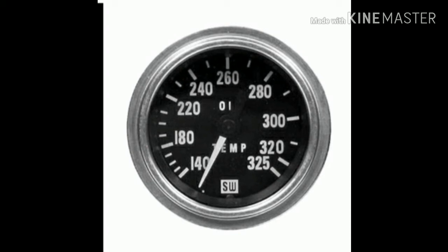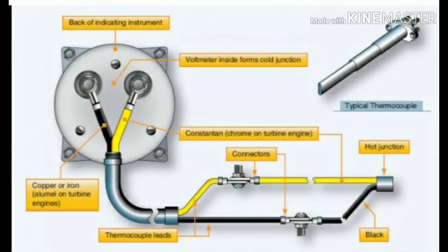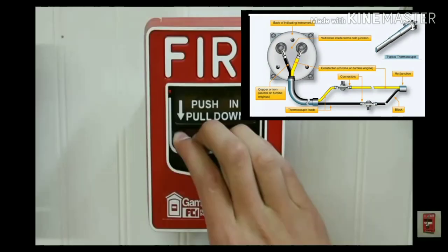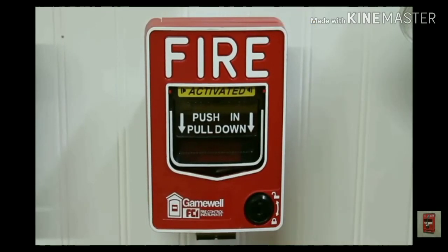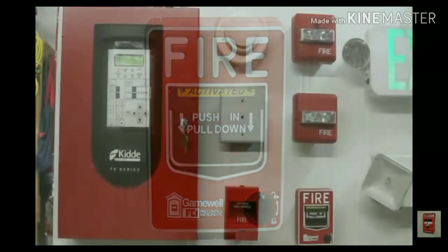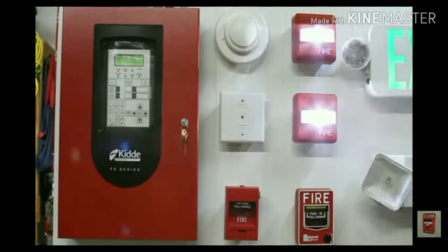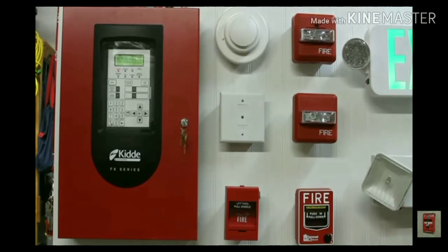System test. The integrity of the continuous loop fire detection system may be tested by activating a test switch in the flight deck that switches one end of the sensing element loop from its control circuit to a test circuit built into the control unit, which simulates the sensing element.